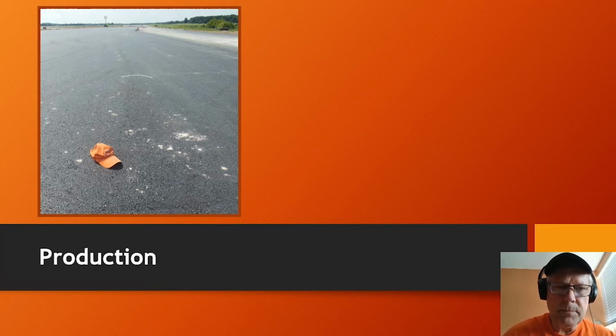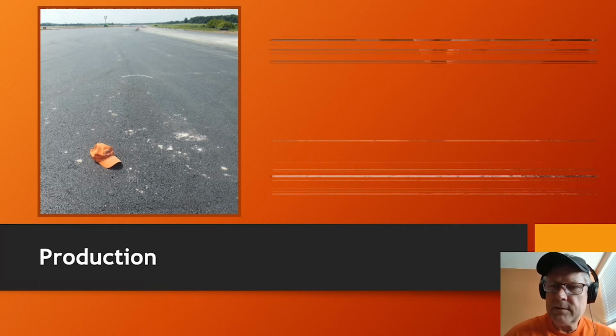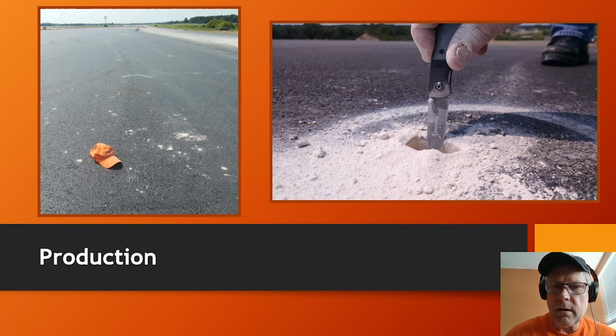Dust balls show up in the field, sometimes just a few areas, sometimes it's throughout the project. If you have a thin surface lift, almost inevitably all of them will fail within the first winter. Sometimes you can just core holes and replace with hot mix asphalt or hot poured rubberized joint sealant. But if you have a thicker lift, unfortunately you're going to be looking at potentially removal and replacement of the asphalt to make sure you get all of the dust balls out of the matrix. So we don't want to do that. This is a knife I held once where all I saw was a tiny little white dot at the surface of the asphalt. I just kind of rotated the knife around and it began to fall into a dust ball. And generally they're about the size of a golf ball.